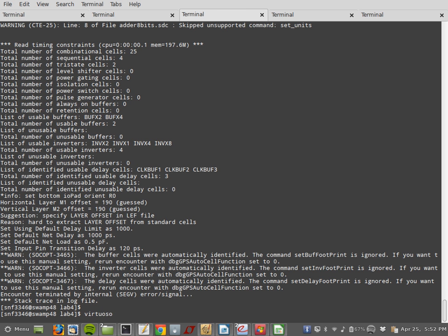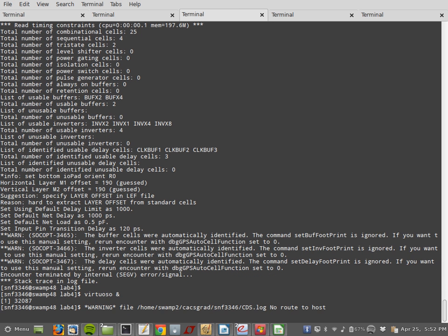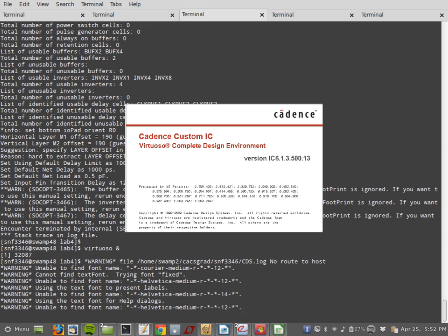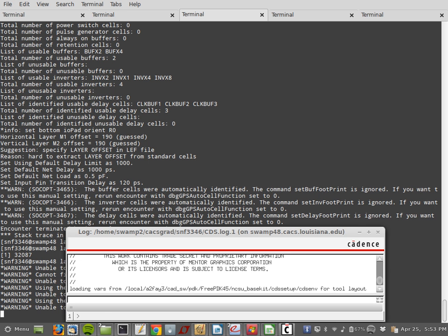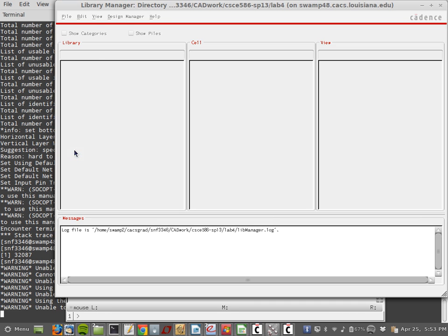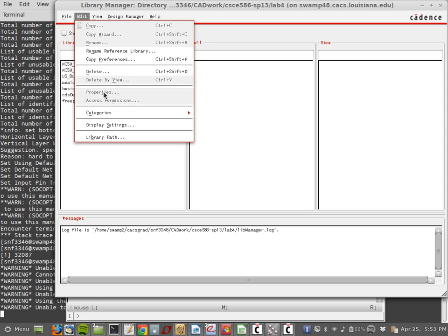So the last thing I wanted to show you is how I can take the Verilog output from the synthesizer, the gate netlist, and get it to work in Cadence. Now when you start Cadence next time, because I will work on fixing this, you will have a new library here called symbols. But because we don't have it here, I'm gonna add it manually. You don't have to add it manually.